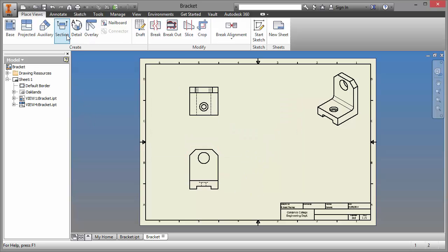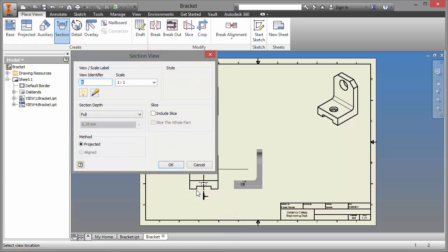I'm now going to create a section view, so it's asking select a view. This is the view I want to section, and now it's asking me the endpoints of the section line. Now I don't want to click on that green dot there in the middle, I want to hover over it and just come up a little bit. You'll see the dotted line now, and then come straight down till I get the perpendicular side. Right click, create, and now you can see it wants to create again just a side view, but this time sectioned.